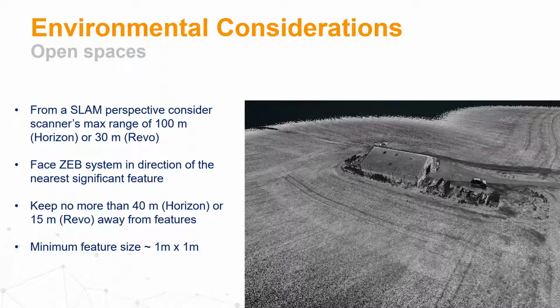Again, if this is an outdoor capture, something to keep in mind with Horizon, you wouldn't want to be more than 40 meters away from the building. With Revo, you would need to be closer, maximum 15 meters away from the feature.